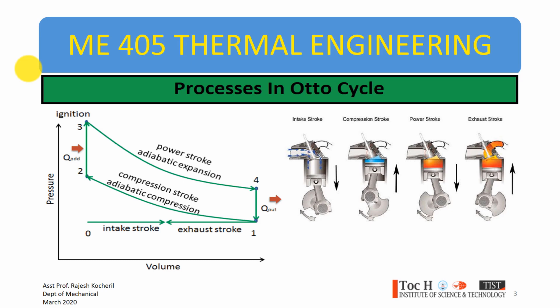When the piston moves down, at that time there is a difference of pressure, delta P. The atmospheric pressure will be higher than the pressure inside the cylinder, because when the piston moves down, it acts like a vacuum pump. So because of the difference of pressure, air from the atmosphere moves in, and when the cylinder is filled with the charge, its inlet valve is closed.